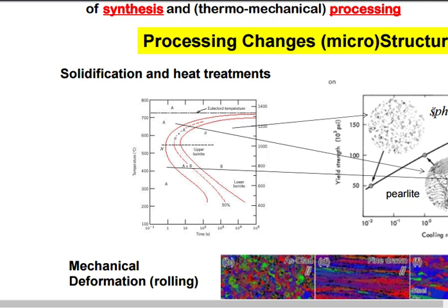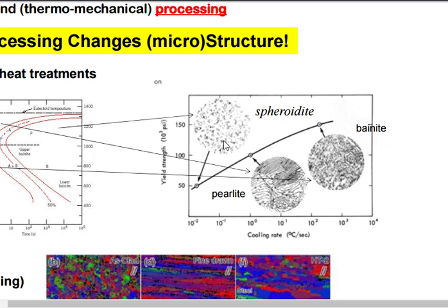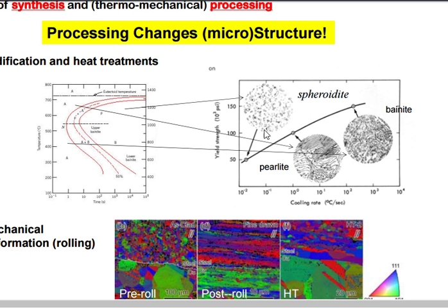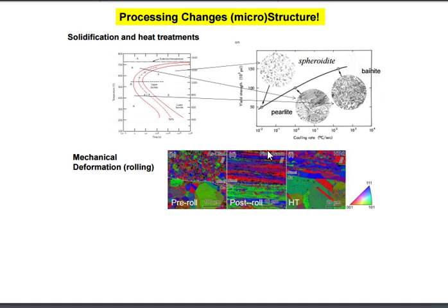You don't need to concentrate on the terminology right now, but the main thing you need to grasp is that there are different varieties of microstructure that can be controlled with the cooling curve, so with the cooling rate. So we have low cooling rate, medium cooling rate, high cooling rate, and for those different cooling rates, you have different microstructure. This particular concept is for steel right now.